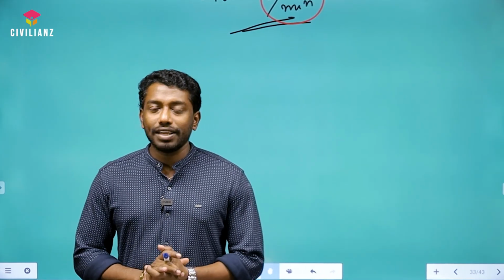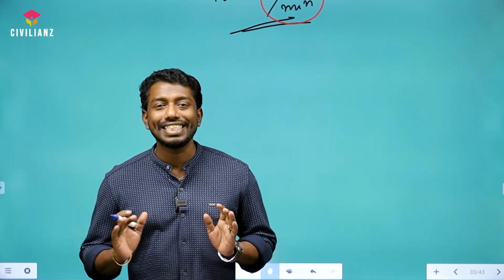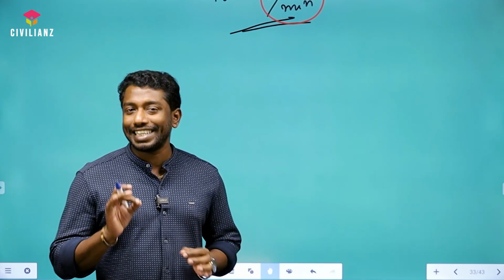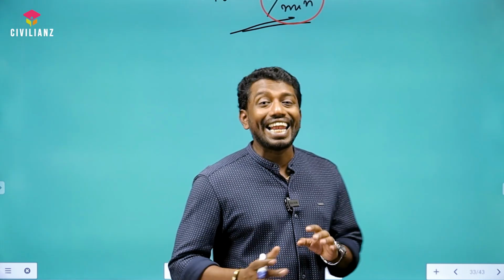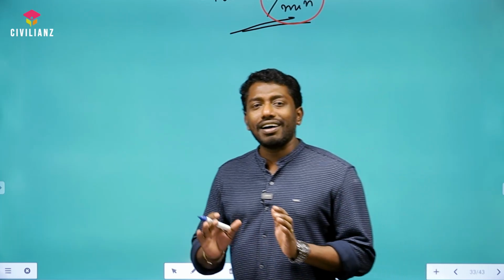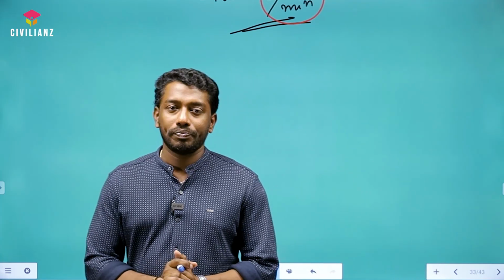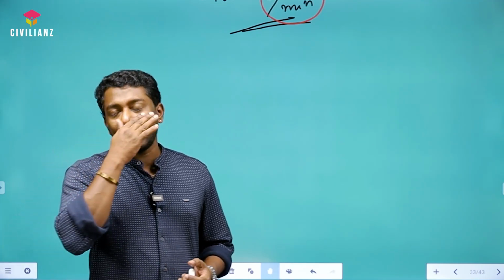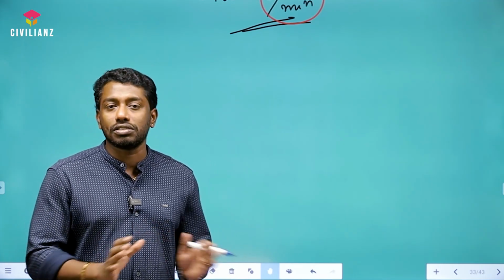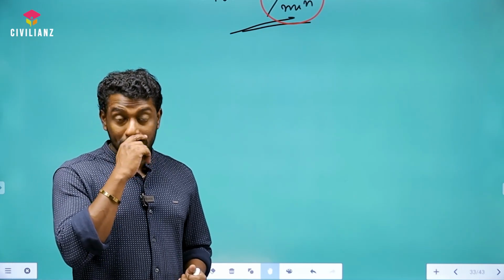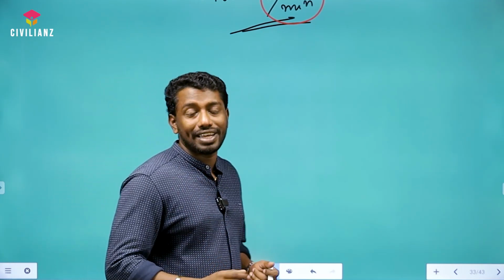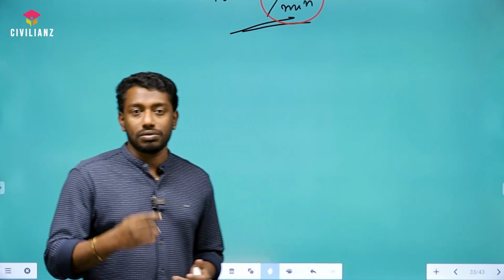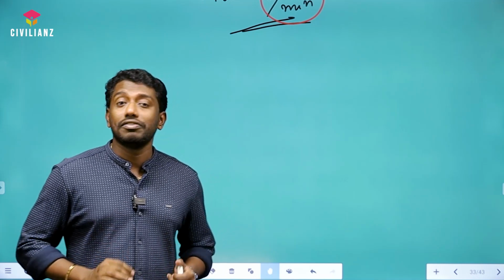So next we are dealing with design period. What is design period? Design period means it's a utility period. It's a useful time period, it's lifespan. While considering the design period, we will not make it too large or too small. Too large makes it a burden for the present users while it's construction and operation. And if you are making it too small, it needs expansion soon. So it is not economically feasible.